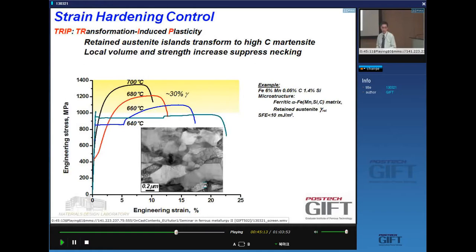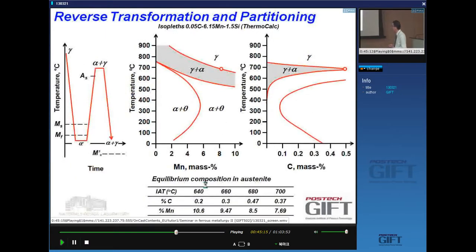And the reason why is because the properties of your austenite are so dependent on the temperature at which you form it. And so these steels are made in a very simple way. You austenitize them, you turn them into martensite, and then you do an annealing. Yes? And when you do this, you can choose at what temperature you do this.